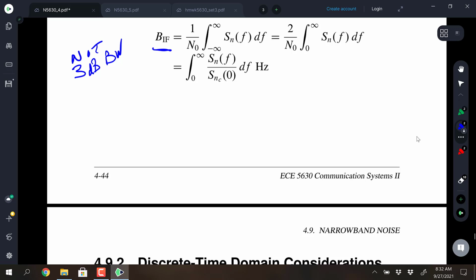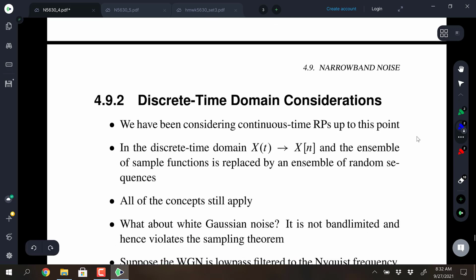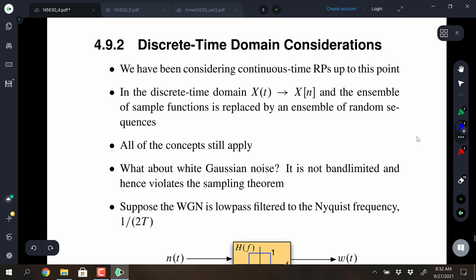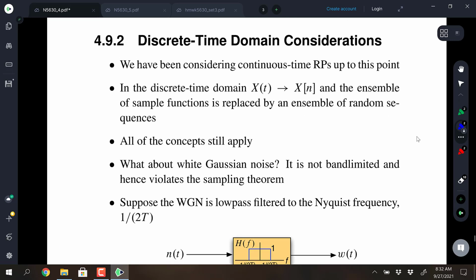You want to make sure, because if there's a difference in there, you want to take that into account. Why is that important? Well, it might only be a few hertz, rather than being 5 megahertz. If it was a noise equivalent bandwidth of 5 megahertz, the 3 dB bandwidth would probably be less than that.